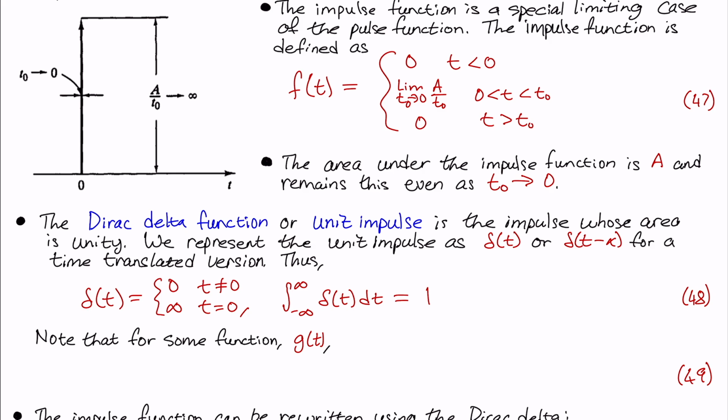And then from here you can find the impulse function. The impulse function would be that constant A multiplied by our Dirac delta. So the Dirac delta is really used to represent impulses: very, very sudden changes in an input to a system that are of very short duration. Things like impact between particles are impulse-type problems as well. They can be represented by Dirac deltas.